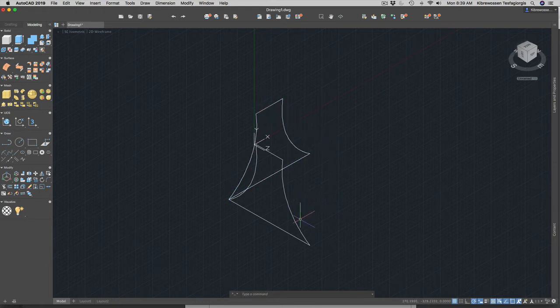Something that I did not mention is, let's create a solid object so that we can do the intersection function very easily. For that, there is a function called region. Region means this is where polyline is very handy. We already have the line function, so why do we need a polyline function? The polyline function becomes handy because, especially whenever you are trying to create a three-dimensional object, the polyline can be converted to region.